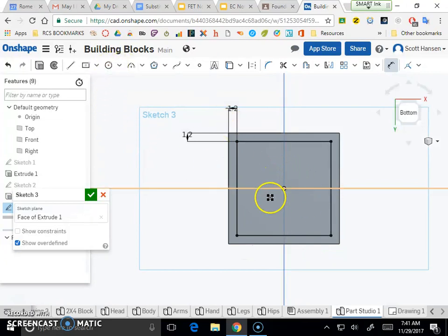I've also got that cylinder in the middle, and that cylinder's got thickness as well. And I'll use a center point circle for that. Again, having this rectangle lined up with the origin makes it easy to do this design. So I'm going to create the big circle. I'm going to dimension that. And then I'm going to create another center point circle inside that to provide the thickness for that cylinder. And so again, you should have those measurements. If you don't have those measurements, you'll have to get your calipers out and take those measurements again.